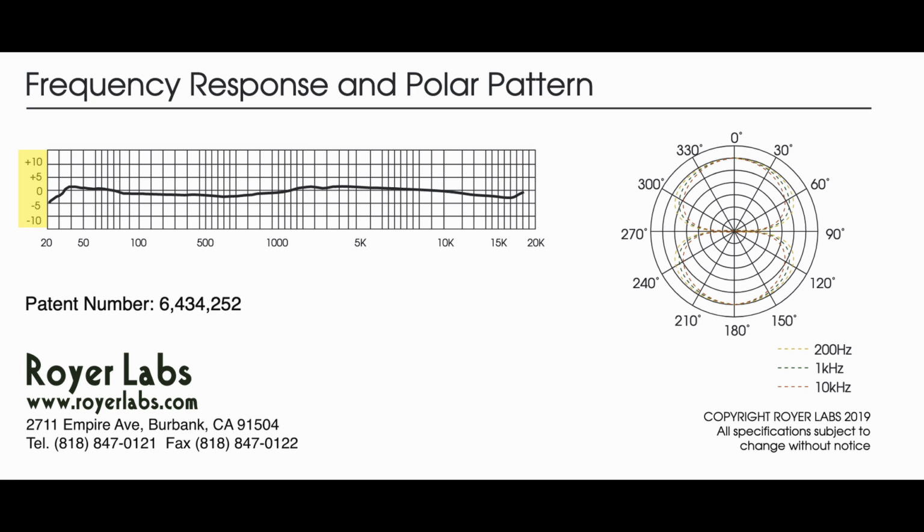If we look at the scale on the left, we can see that these scoops, bumps, and dips are all less than 5 dB. If I had to guess, I'd probably say it's only within a couple of dB across the board. Even without picking up the mic, based upon this information, we can say that the mic should sound pretty smooth. With the exception of the extreme ends, there are no sharp upticks or drops in the response.